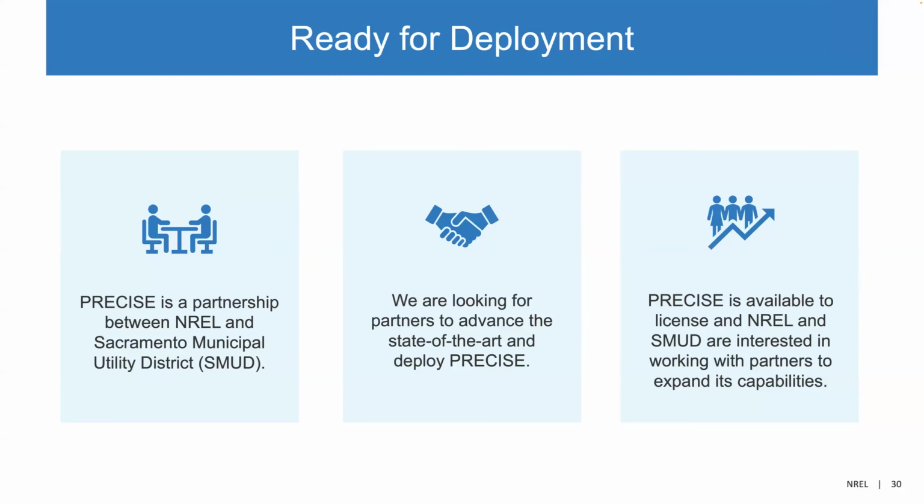Okay. So first of all, do you need power flow models to use Precise? I would say no, but it would help. So we've worked with a lot of different distribution utilities here at NREL with a lot of different quality of data sets. Some utilities we've worked with just have GIS, and from the GIS, we've been able to build out power flow models. Other utilities have good primary models, and we're able to use those, but they don't have any secondary information for which we've created heuristics or synthetic secondaries.